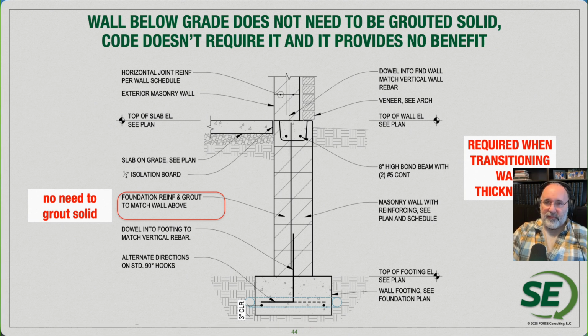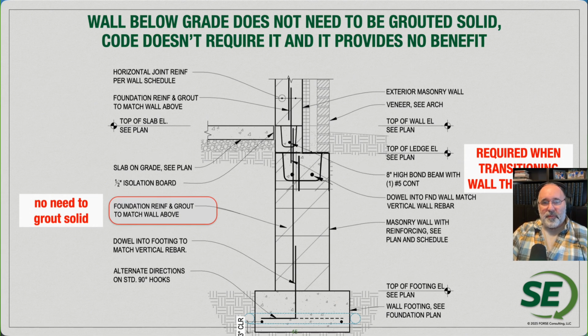And certainly as that wall cavity gets larger, that's when we do get to the point of maybe using 12s or 16s for the stem walls or basement walls. Again, being very careful with the dowels and reinforcement location. Maybe the reinforcement needs to be offset in the stem wall or basement wall below, so that it can be centered in the wall above. That is going to be a really important step to make sure that, if you want to have a fully fixed base, you go ahead and utilize that for your design.